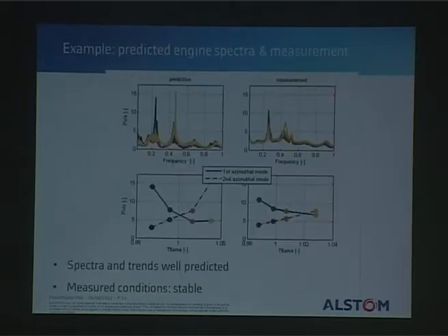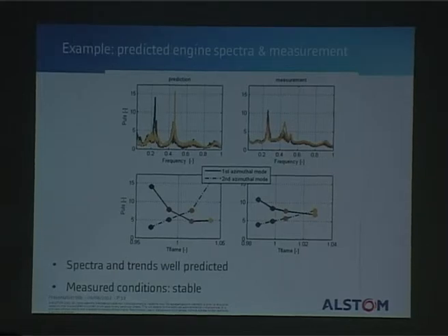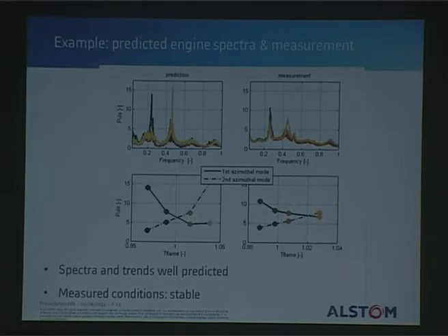So often we are in a range that is quite stable, and then okay, it's stable, the eigenvalues are fine, so there's no problem, but then this guy will complain and say, no, it doesn't work like that. You can also have problems where, even if you have completely stable eigenvalues, all of a sudden things start growing. We didn't look at the time traces in detail, but sometimes you see some kind of bursts of things that go up. I don't have experience that they go dramatically up, but still, relying only on eigenvalues to say things are stable is not that safe.